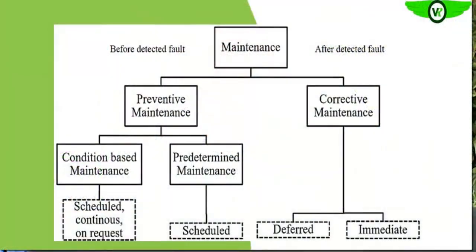Okay, so the test results that you get under your condition-based maintenance, you can use to schedule your maintenance program. Then when you come to the right part, you see corrective maintenance, it has failed. Once an asset fails, they usually take that fire brigade approach. So we want to fix the problem, and in doing that, we can introduce other problems, maintenance-induced problems in the facility, and we can also incur more costs.